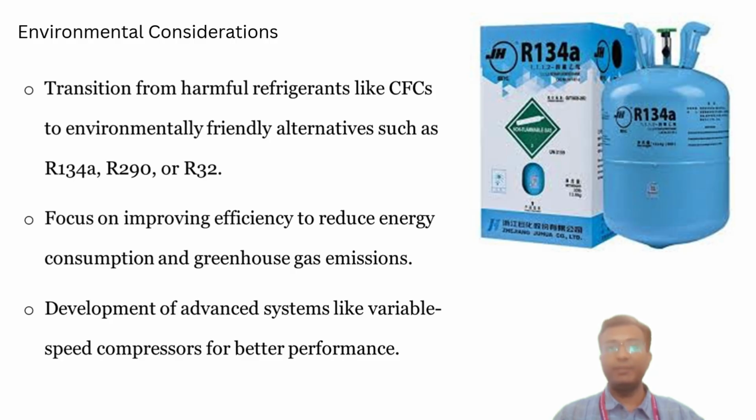HFCs, their replacement, are better for the ozone, but still contribute to global greenhouse gas emissions if they leak. Now, the industry is shifting to eco-friendly alternatives like R134A, R290, that is propane, and R32, which have lower global warming potential. For example, R290 is used in some modern refrigerators because it's natural and less harmful.